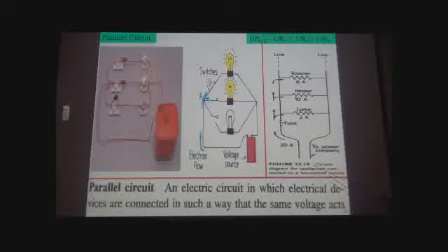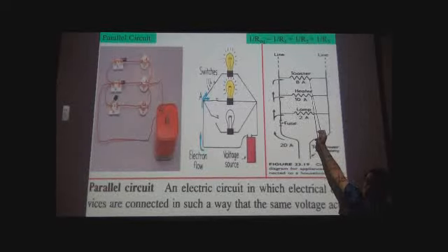At your home, typically what happens is all of your electrical appliances are hooked up in this kind of a fashion where you have your lamp drawing 2 amps from the lines coming to your home. The power company is supplying you 20 amps at 120 volts. Here's a fuse. So the electrons travel here. Some of them go through the lamp, some of them continue on, then go through your heater, some of them continue on and go through your toaster, and so on.